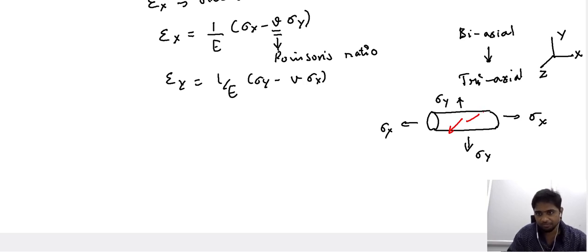So maybe a better representation. Yeah. So it is along the z-axis. This is the new stress that we impose, and since tensile stresses are being imposed in all three directions, we refer to it as the triaxial tensile loading condition.